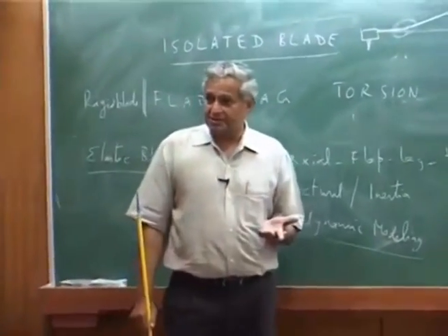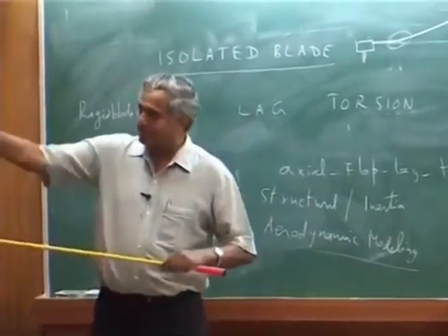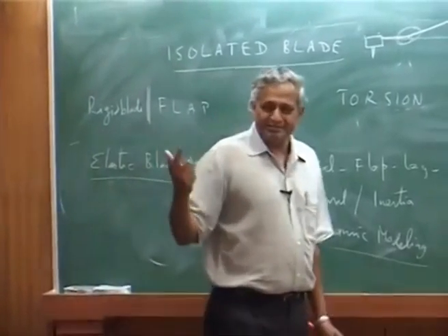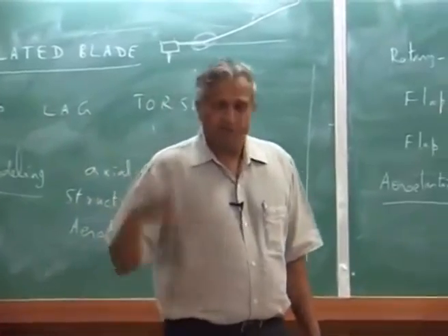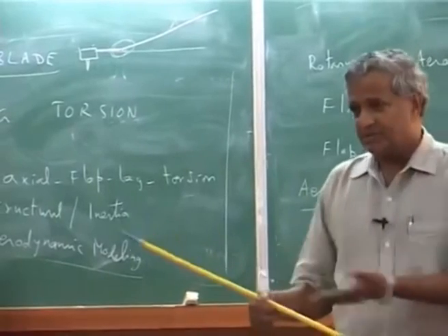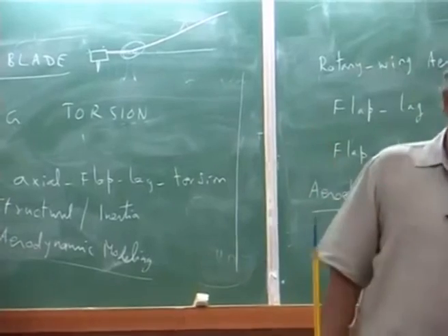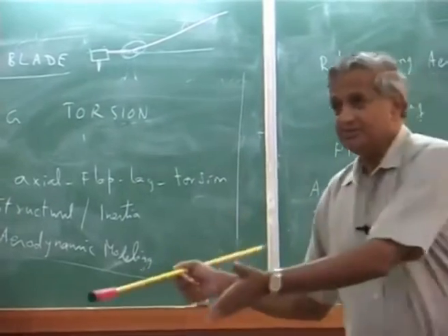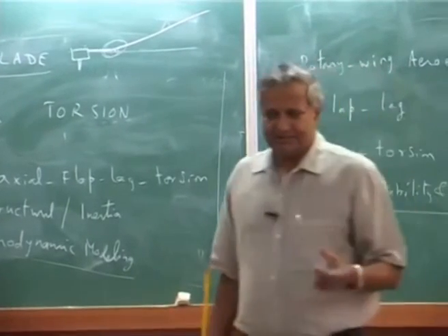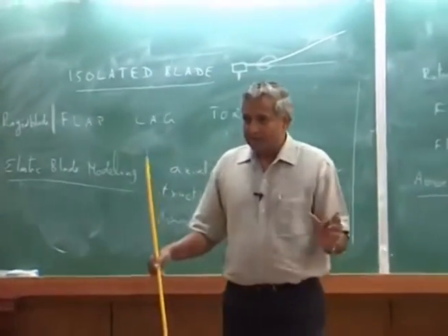If it is an articulated blade, then you have to calculate because the root hinge movement is 0. Then the blade may have some other point where the bending moment will be higher, but that is usually not very high. You have to make a measurement. You put a strain gauge there and make a measurement, because in that test I told you, they measured at 50%, 55%, something like that. Bending moment at 50%, and then try to correlate how your theoretical value matches with the flight test. But number wise, I don't see your question really. Is it a numerical value you are saying?